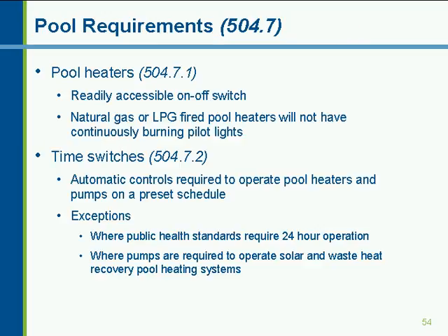There are a number of requirements for swimming pools. Swimming pool heaters must have a readily accessible on-off switch. If you've got a gas-fired pool heater, you can't have a continuously burning pilot light. It must have an intermittent ignition device.